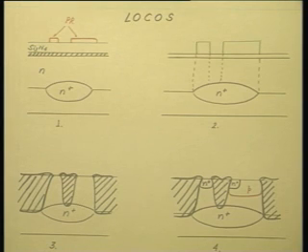So, this is a recessed oxide LOCOS isolation technique. Recessed oxide is used in order to improve the planarity of the device. Of course, without recessing also you can use the oxide isolation technique. In that case, the top surface of the oxide will rise above the actual device surface. So, there will be a loss of planarity. But of course, if you do this recessing, then you have a slight non-planarity on the surface, which is caused